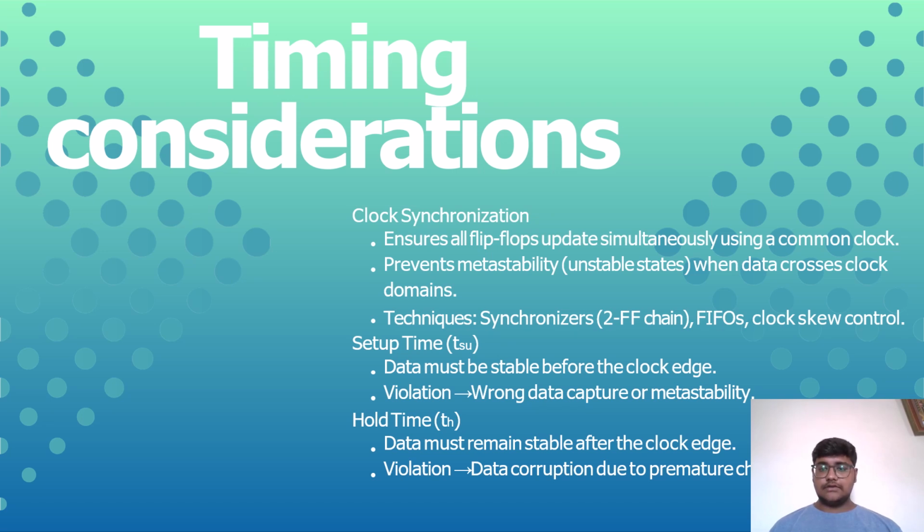We ensure all the flip-flops update simultaneously using a common clock. This prevents unstable states where data crosses clock domains. Data must be stable before the clock edge. On violation of this condition, wrong data capture and unstable states will occur.